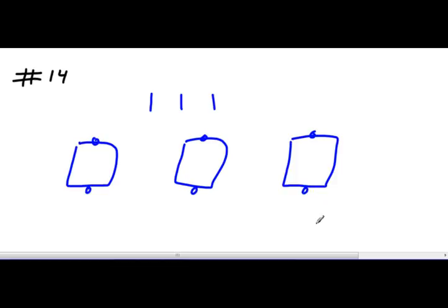So if they're NOTed guys, and I've got that NAND gate there, that means that whenever I get to 7, I'm going to reset and go back to 0. So I'm never going to see 7. It's going to reset and go back to 0. Well, the first flip-flop, isn't it connected to the Q? The NOT one's going to go to 0, go back to 1.